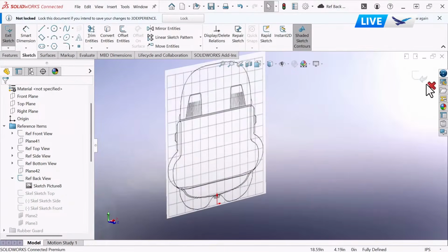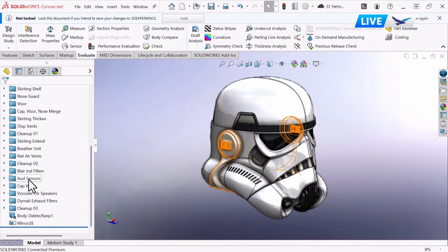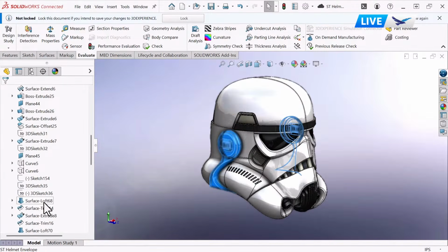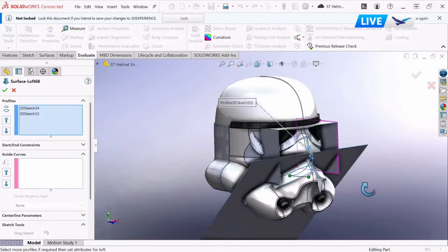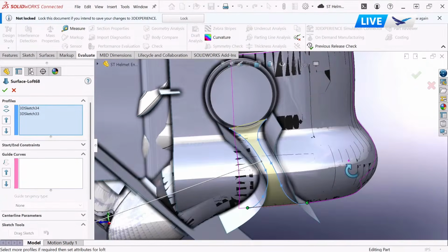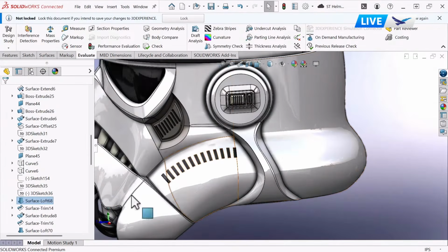Try to look at a feature tree with 500, I'm going to go with 20. 520, you nailed it. Features in the tree. So you can organize them by what step you're on, like what part of the design, what tip we're doing currently, whatever it is. So you can organize those folders just to keep it clean.